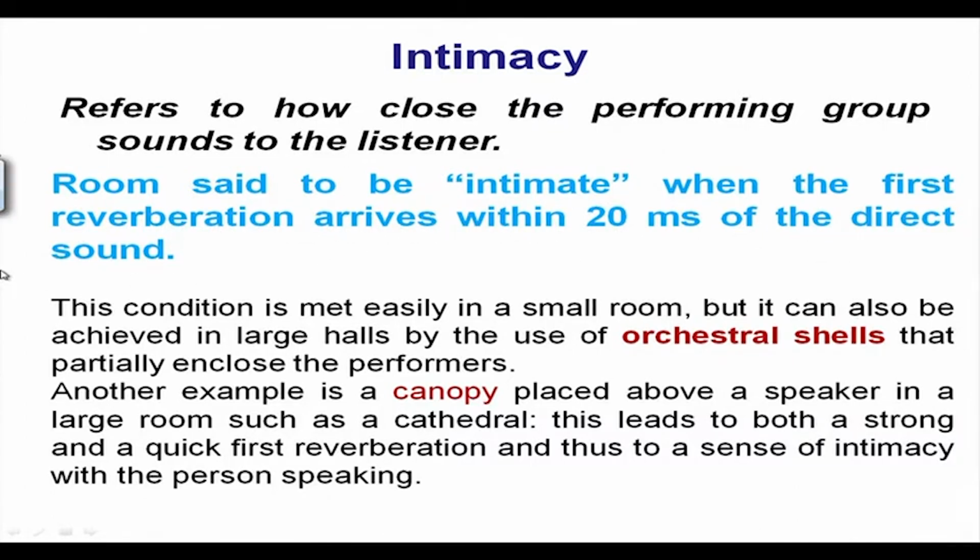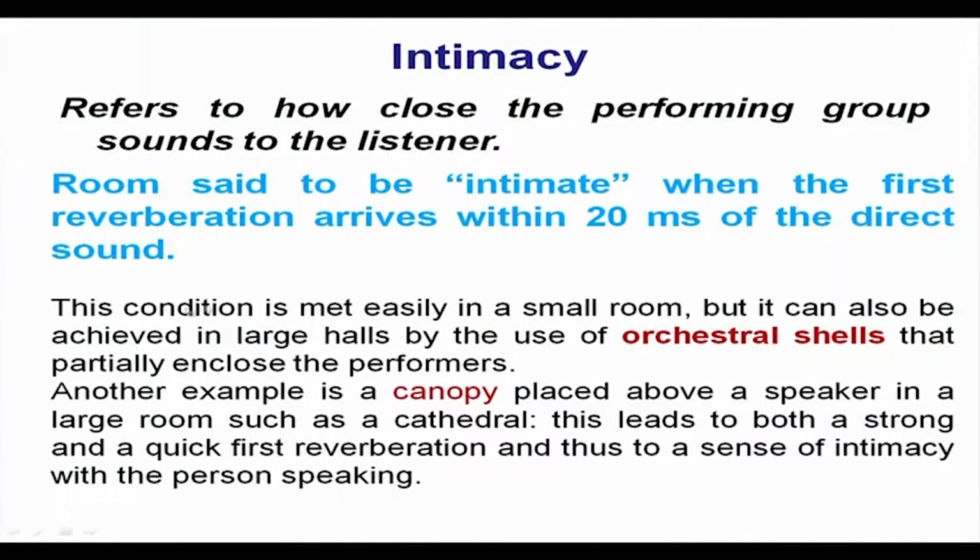So, if the first reflection to the listeners arrives within 20 milliseconds, I make an arrangement of all the reflectors such that the time difference between the direct sound and the reflected sound is 20 milliseconds, then a person will feel intimate with the orchestra performing on the stage. This condition is met easily in a small room, because the reflection path is shorter. But it can also be achieved in a large hall by using an orchestra shell that particularly encloses the performers.